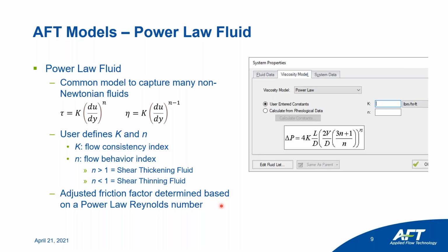Then we can plug that friction factor into our standard Darcy-Weisbach loss model. If you're interested in seeing more about some of these equations, you can look at them in the help file for Fathom or Impulse. I just got done refreshing some of our documentation, and we've got some good materials there to show what those equations look like.